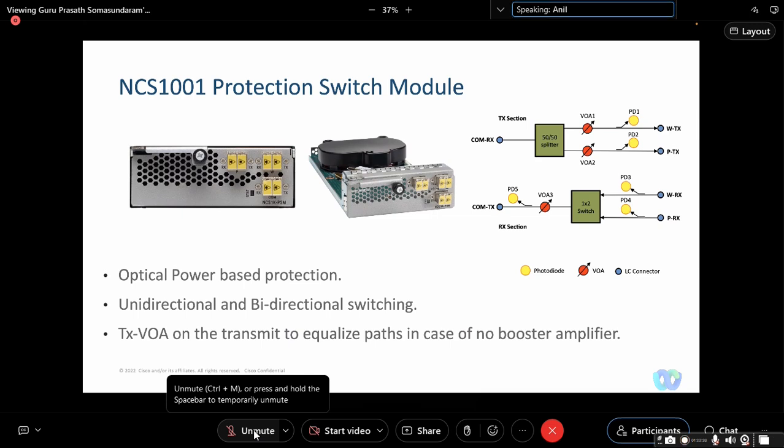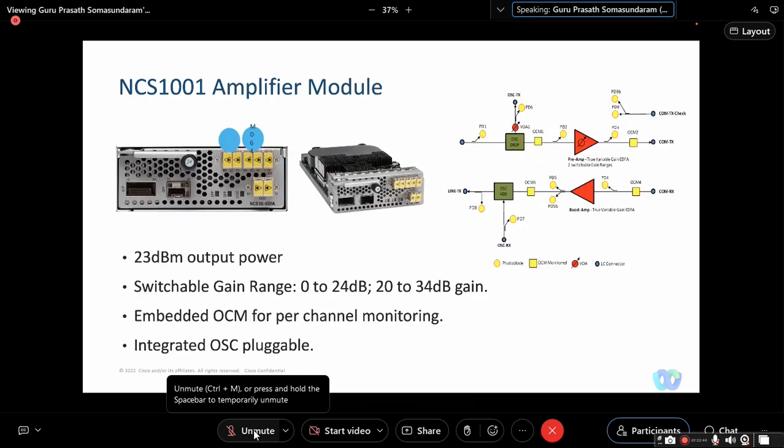Can you elaborate on whether there is any functionality in the EDFA that monitors the line side fiber? Like OTDR functionality or RFMS? There is no OTDR functionality directly on this particular card. We have a separate OTDR module in this line system that you can use if needed. But at least in the circuit that is deployed, there is no OTDR related functionality. What is available is the power monitoring and the channel monitoring.